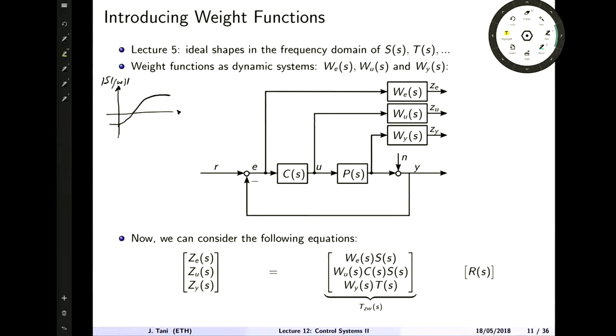Just by intuition. I know it's not easy, and actually it's hard to compute infinity norms of systems by hand. But where do you see the infinity norm of a transfer function? Yes? Maybe it's right, but I didn't understand what you said, so I'll try to answer it. So it's this, right? So it's the maximum value of this transfer function.